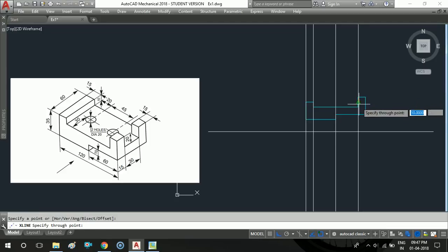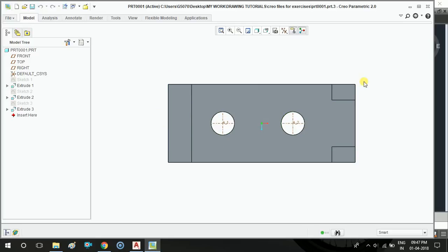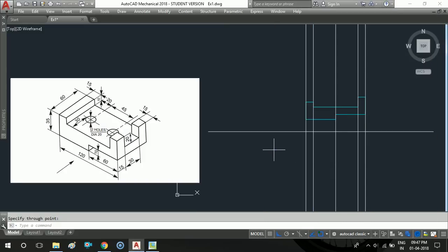So here I am drawing construction lines in between which we can get the required drawing. First we try to draw the rectangle, because the view is totally like a rectangle in which we get some lines based upon the shape of the object. At any convenient location below the XY reference line, I have initiated the line, and in between the extreme positions of the front view we need to draw. In the downward direction, the length of the object when you see it in top view is 60 mm. Next, join to the construction line and to the initiated point.